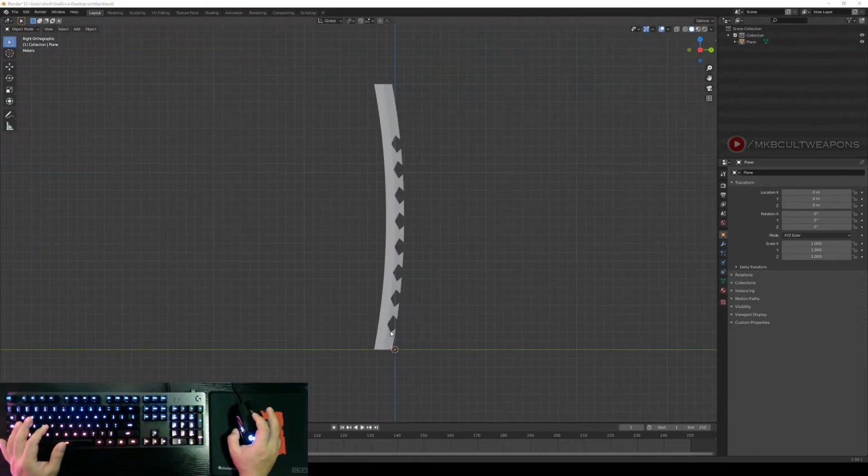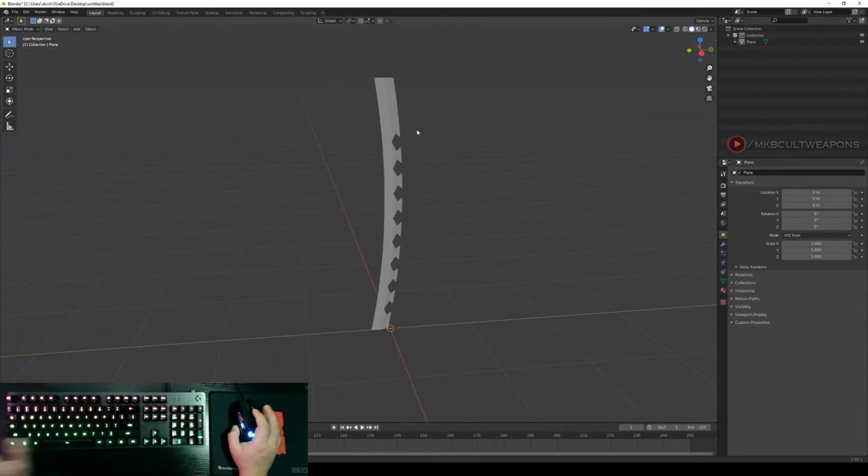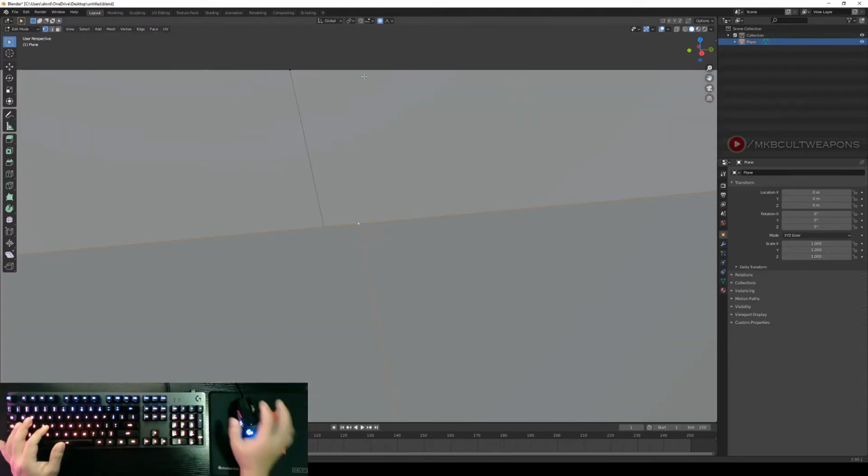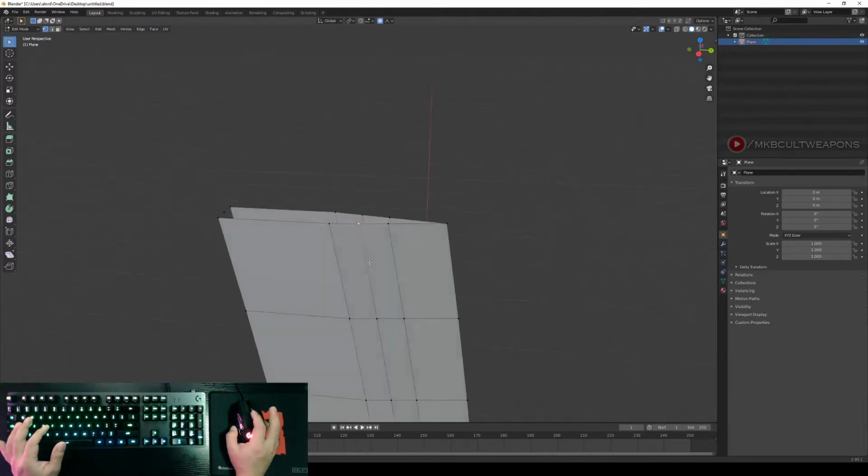Going to continue on the pattern here. We need to fix the pointed part first. In order for us to do that, we need to select our mesh, press Tab to go to edit mode, click the single vertex here, and press this button here so that we can focus on what we are working on.